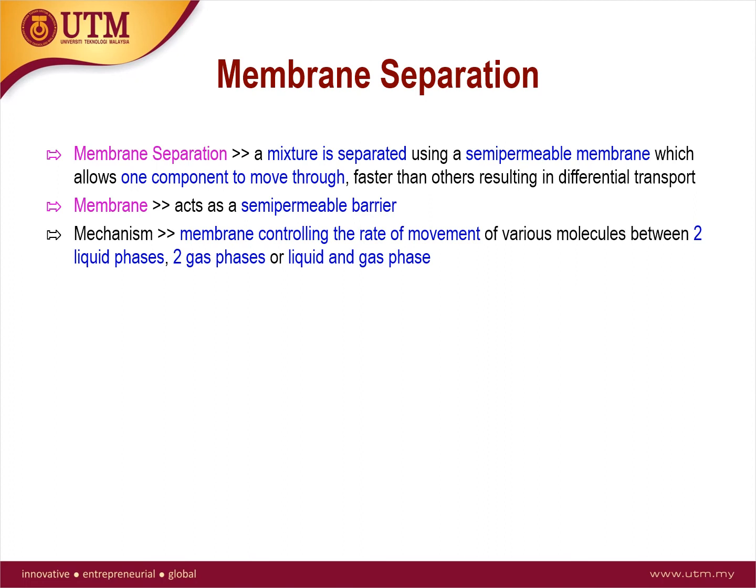Membrane separation processes operate without heating and therefore use less energy than conventional thermal separation processes such as distillation, sublimation, or crystallization. The separation process is purely physical, and both fractions, which are permeate and retentate, can be used.